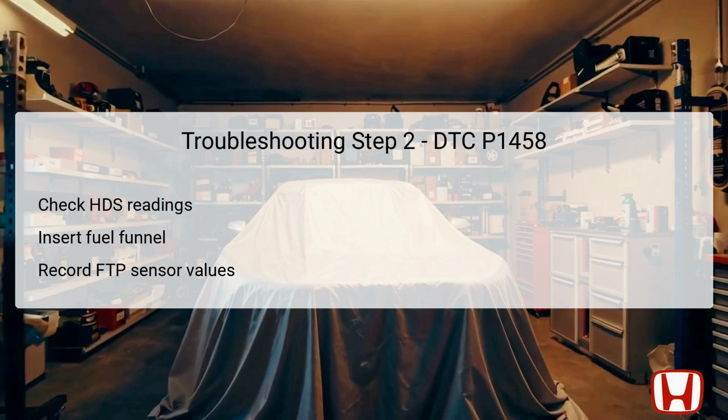If the readings fall outside this range, it is a strong indicator that there may be an issue with the FTP sensor itself, signaling the need for further inspection or replacement. Ensuring accuracy in this reading is crucial as it lays the foundation for subsequent troubleshooting actions.